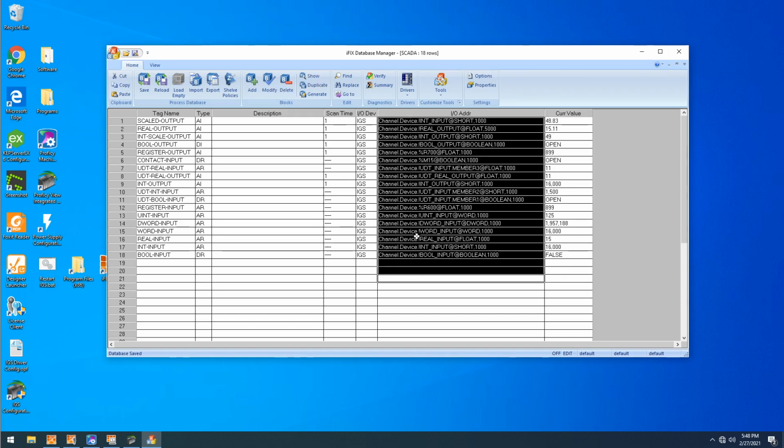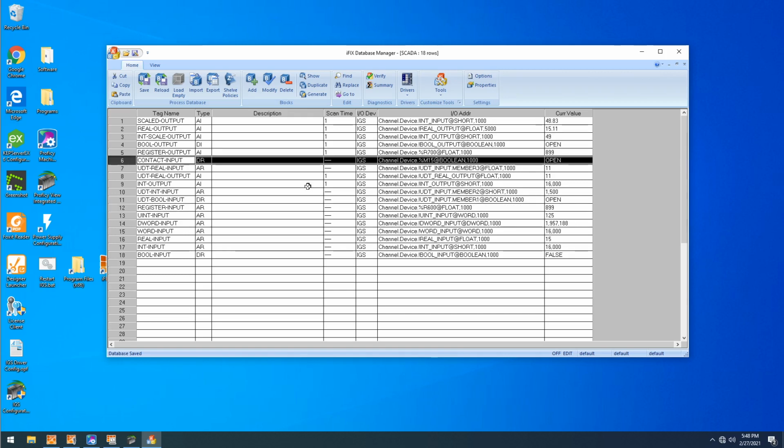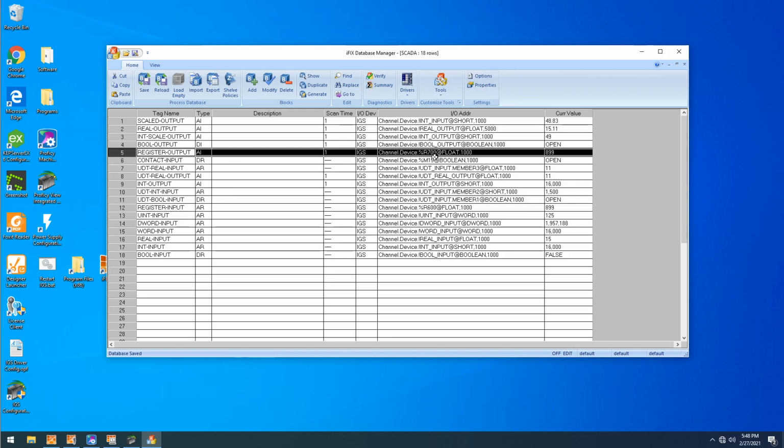The important distinction between symbolic variables and variables in our PLC that have a reference address tied to it is that anytime we have a symbolic variable, it's always exclamation point followed by the variable name, whereas for a referenced variable, take this register input, it's just %R because it's the %R table followed by the address of that table. Even here for this motor contact or maybe another register. So that's the distinct definition.